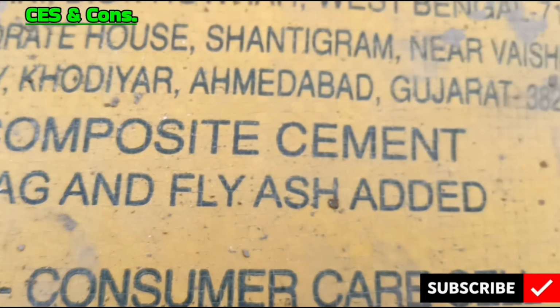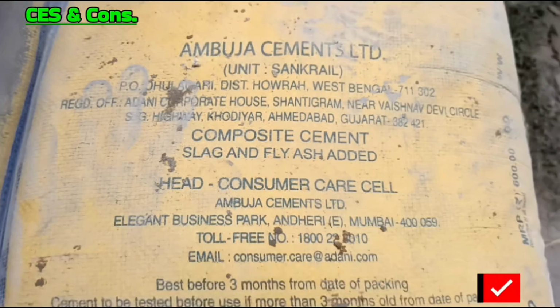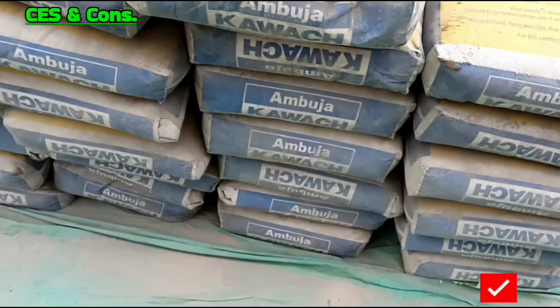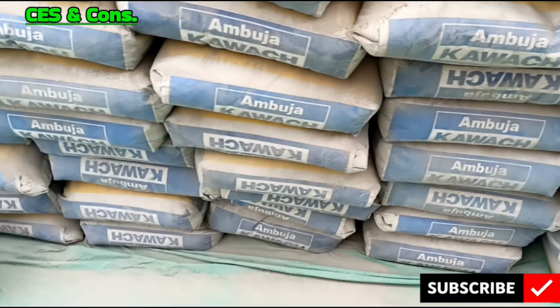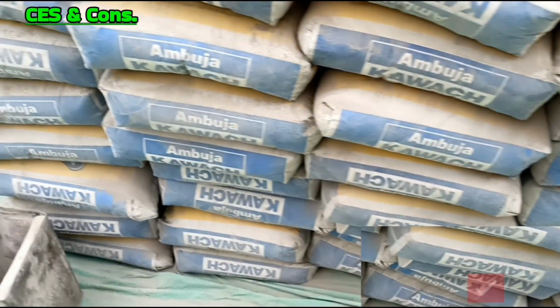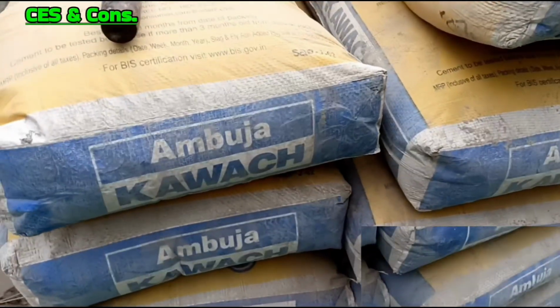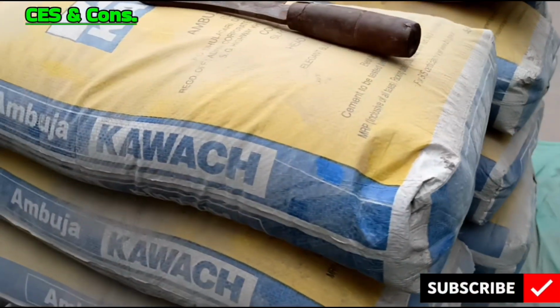Number 3. Compressive strength. This is as per 4031 Part 6. For OPC 33 grade, 33 MPa in 28 days. OPC 43 is 43 MPa at 28 days and OPC 53 equal to 53 MPa at 28 days.